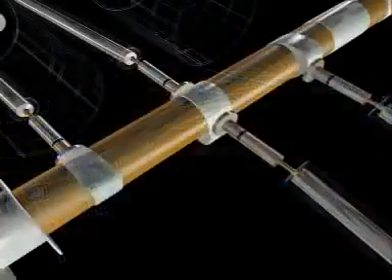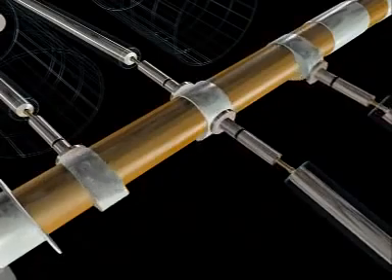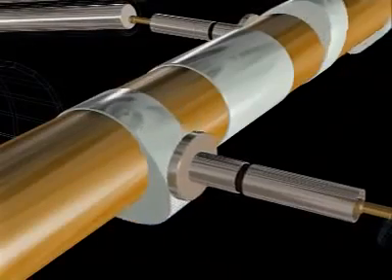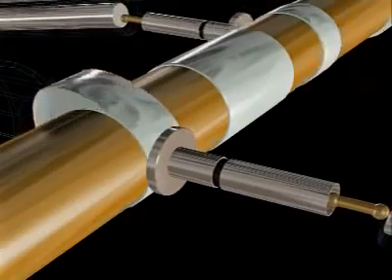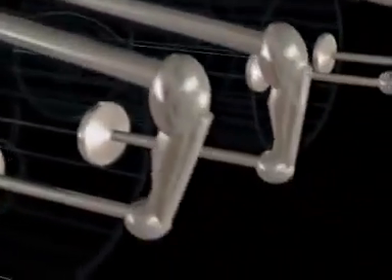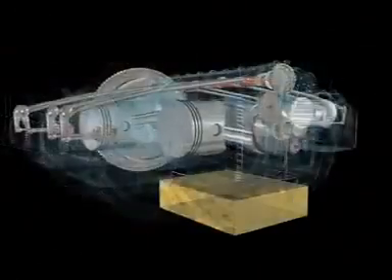The camshaft has a vital role within the engine, controlling the opening and closing of the inlet and exhaust valves in the combustion cycle. The shape of the camshaft has been designed to operate against a follower. The follower then moves a rod connected to a rocker mechanism to allow each valve to open and close.